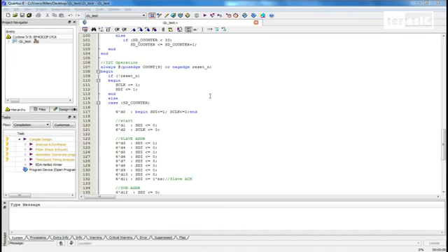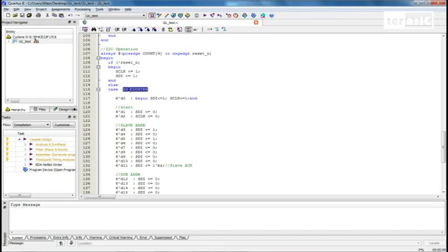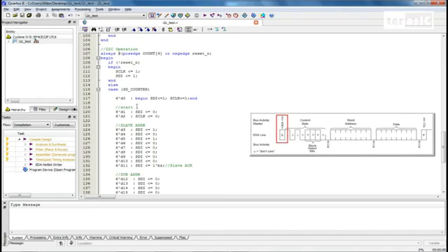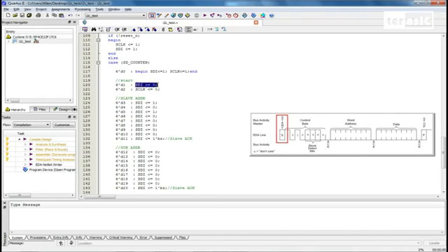So getting into it, we have our case, which is based on our SD counter. Now, the default condition is that SDI and SCL are both high. These correspond to our SDAT pin on our EEPROM and our S-clock pin on our EEPROM as well. So they're both high in the beginning when SD counter is equal to 0. Now once it starts counting up, however, our SDI is the first one to go down. That is our start condition over here, and SCL can go down as well.